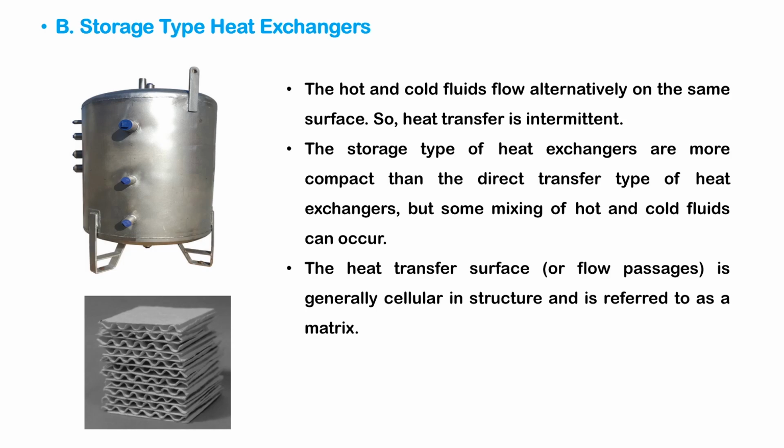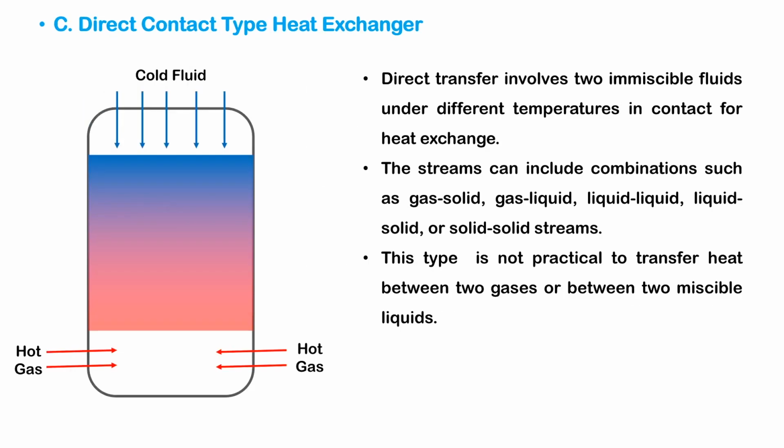Of course, you want to make sure that the waste and the fluid that you want to heat up are compatible. If there are, for instance, impurities or a chemical reaction between these two, you cannot use this. So this may only be applicable for certain types of systems. For instance, if you have hot oil, which is immiscible, and you want to use cold water, that could be one area. So you may want to think about what types of fluids you can use in this kind of fashion.